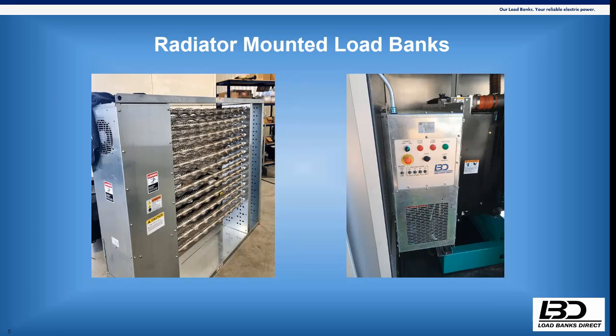If they're going in a factory enclosure, typically they won't have room for them. So that can be another factor in the decision making process: your installed cost versus how much load you need to apply on your generator with the load bank, however big it is.